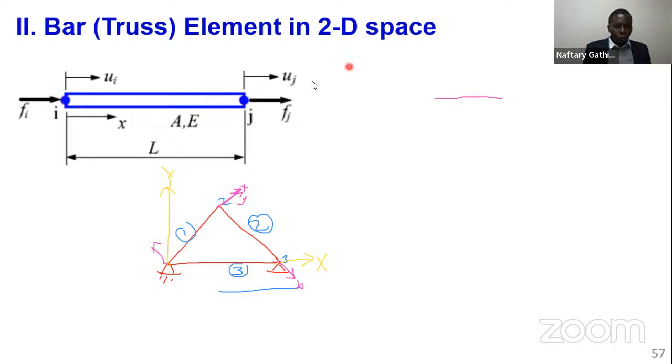So what we are talking of is that for each individual element, we only need one coordinate, the horizontal, to describe its motion, right? And per node, the degree of freedom is 1. Only horizontal displacement. It can either elongate or compress. U can either be negative or positive, but either way, we just need one coordinate to describe the motion or the deformation at one point.